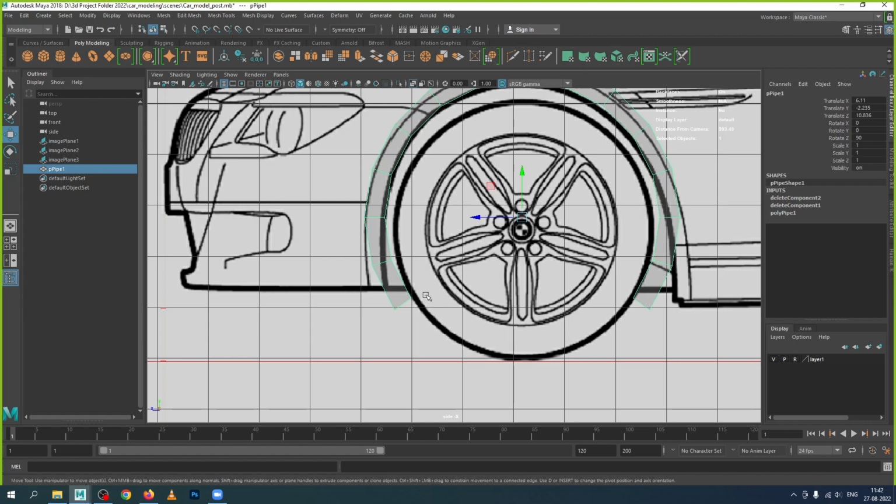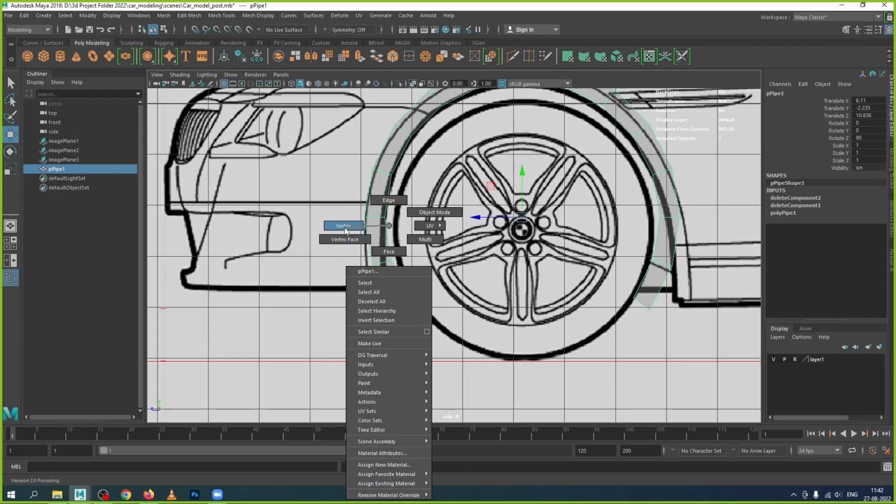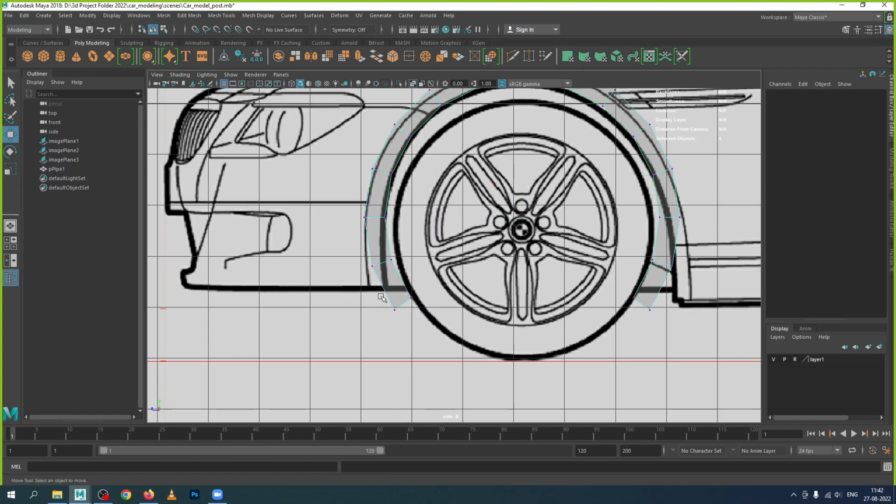After adjusting, then I deleted the faces. I have deleted the faces, side faces, and depth faces we can say. Okay, now I am modifying this one, modifying at the vertex level now. Right click and go to the vertex and try to match this one towards left side now. Little up. Okay, now make selection using marquee selection and then move up little bit and try to match this